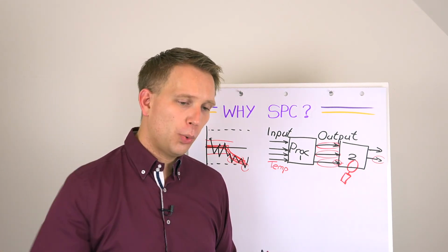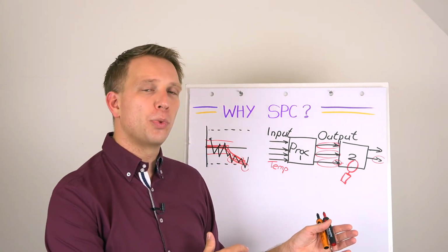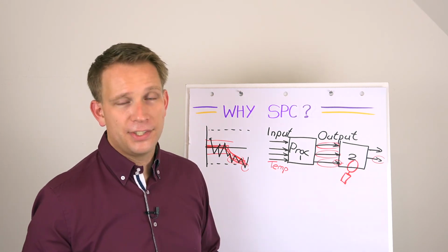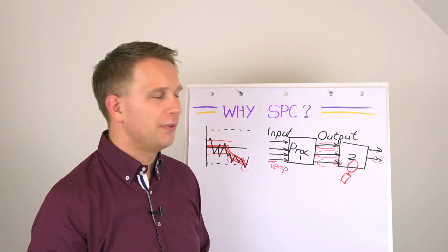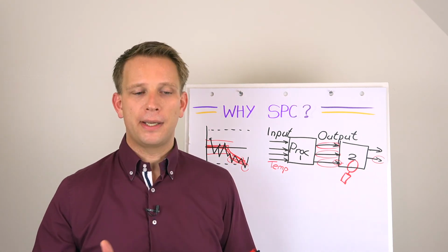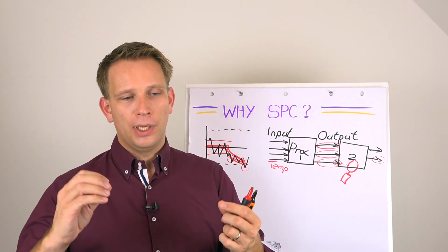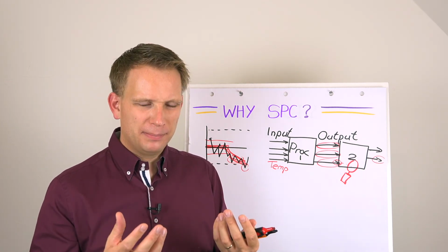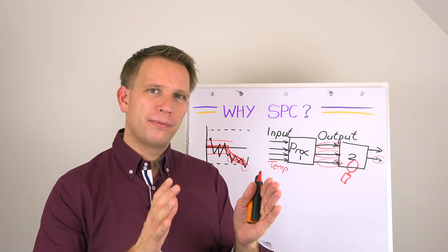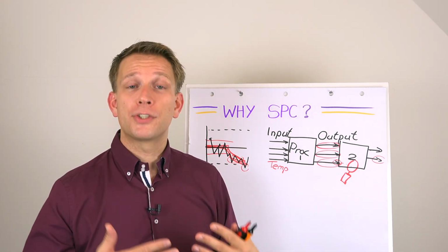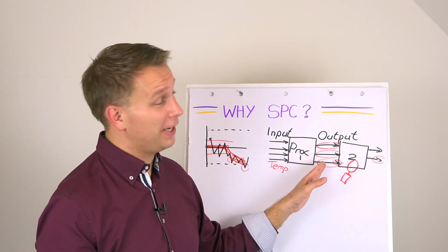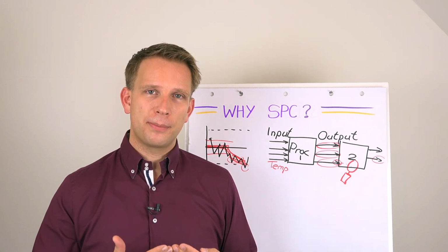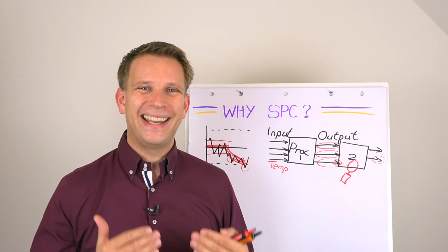Don't check how quick your machine was, how many products were made. That is not something you want to statistically control. That's just money and really a resulting KPI. But do check things like what's the size coming out, or do things fit in each other? What do we see in a sort of minor defect maybe? So all kinds of quality-like parameters of your intermediate products, very nice, and final products. And you do this to make sure that your systems are doing what you expect them to be doing.